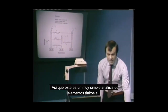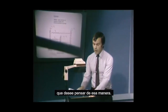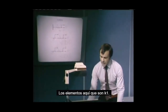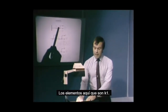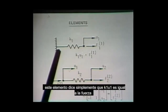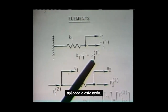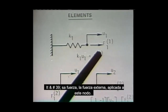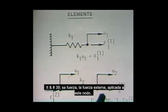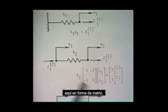So this is a very simple finite element analysis if you want to think of it that way. The elements here then are K1, and notice that the equilibrium requirement for this element says simply that K1 U1 is equal to the force applied to this node. It's the external force applied to this node. The equilibrium requirement of this element, K2, is written down here in matrix form.